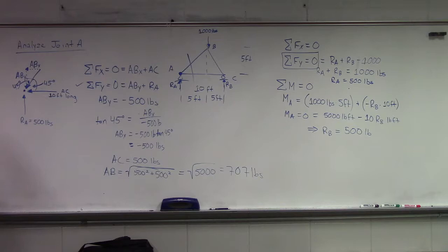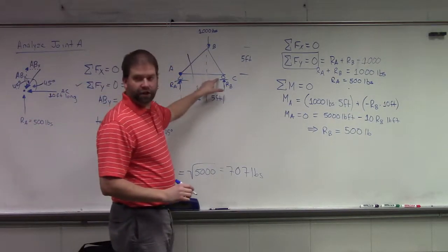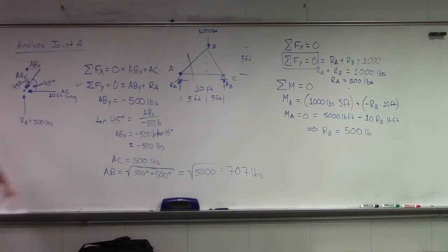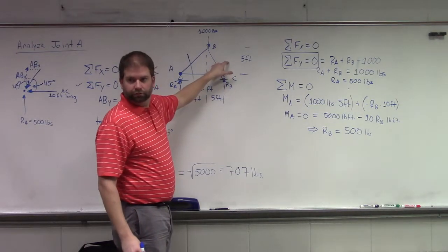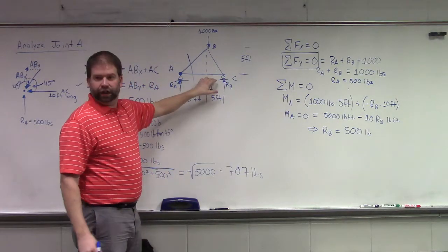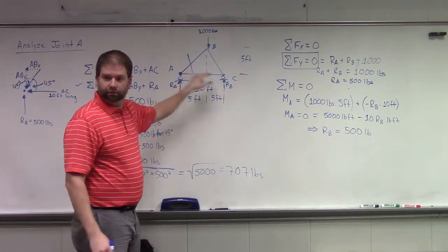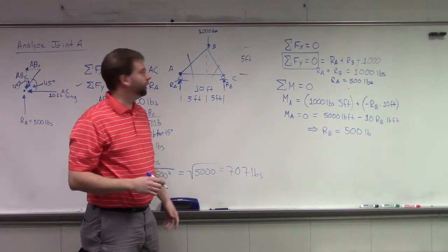Now let's do the other side. Do you wanna do B first, or do you wanna do C next? Well, we already did. 707. C is gonna be the same, right, because of geometry. Oh, because the angles are the same? Yeah. Angles are the same, your member forces are gonna be the same, right? The AC length is still the same. You're transmitting the same load through the system. Okay?